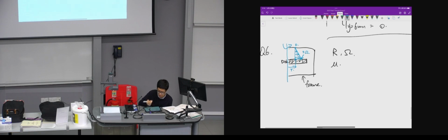Right, so the disk is rotating. We have on the disk an arbitrary point with a distance r from that point to the axis. We have the linear velocity on that point as r times omega, and then it can form a boundary layer, as the problem described, a linear velocity profile. So that means we have a linear shape here. Is that clear? Yeah, cool.